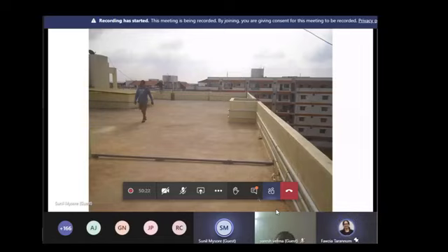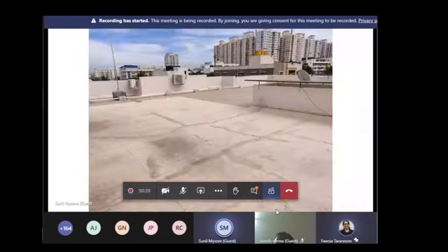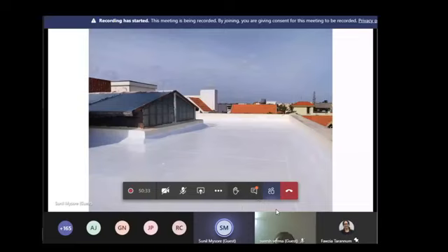This is one of the catchment areas where I work. There's another catchment area where it's kept neat. This is an ideal roof, as a matter of fact. It's coated with white heat seal paint. This also increases the runoff. When we talk about the runoff coefficient of 0.8, 0.85, when you coat it with white heat seal paint, the runoff coefficient actually increases by about 0.05 or 0.06.